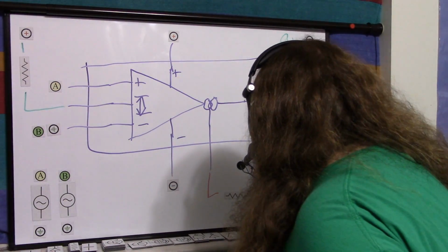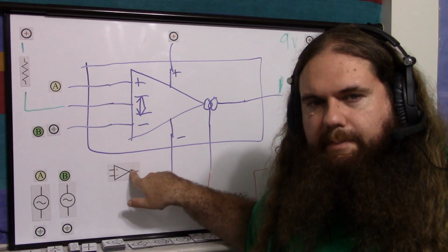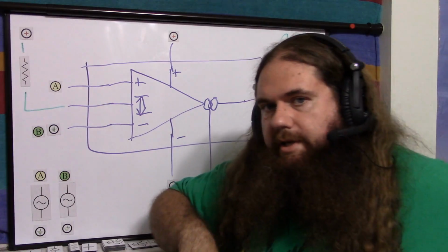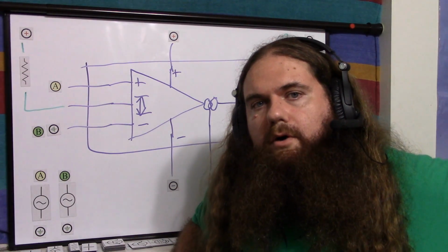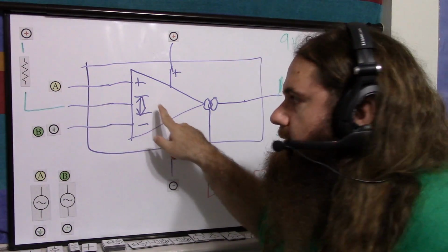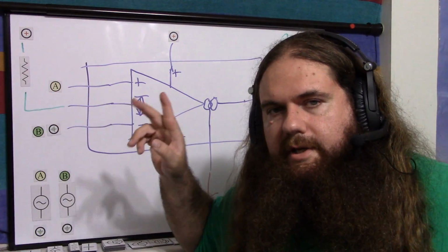This is another reason why I don't bother having these diodes here. It's just like positive and negative power. You just hook it up and you leave it. It's not part of using the chip. The data sheet that I have also recommends 1 milliamp for this. Remember, this is a current in. Just like this diode thing, it's based on the current, not the voltage. It doesn't care about the voltage.